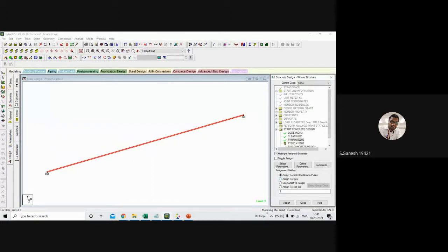When you have a beam element, select the particular beam, give the particular inputs. If you have a column, then select the particular inputs for the column. Example, for beams you have some grade, M25 grade to be poured, or for columns from 5th level to 7th level, you have a higher grade, M30 or M35 should be poured. You need to select that accordingly with the section view or grouping method. Then you select the parameters assigned to that. Since here there is 1 parameter, I'm just selecting it and giving all this part. Right, so this is done.